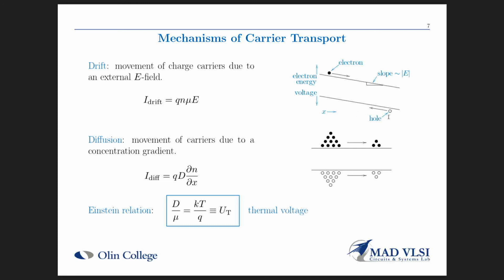The holes, which have an opposite charge, go in the opposite direction, and you can think of holes as sort of like bubbles in a fluid. Actually, that's a very good analogy to what holes are. Holes like to bubble up, so holes like to float up as high as they can on a picture like this. And so these two parallel lines here are actually the lower edge of a range of energies that conduction electrons can have.